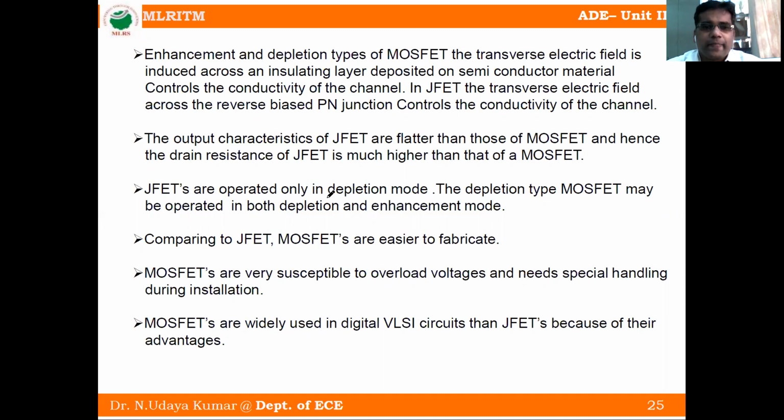The output characteristics of JFET are flatter than those of MOSFET. We will see that JFET characteristics are very flat compared to the MOSFET, and hence the drain resistance of JFET is much higher than that of MOSFET.